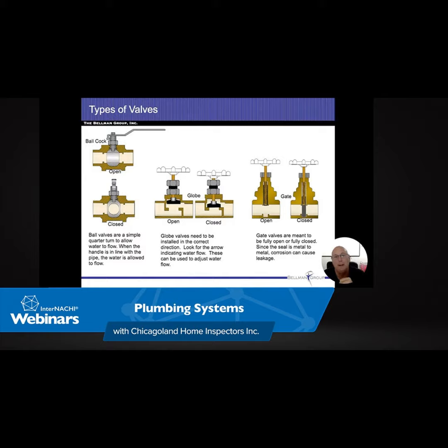But I still have the same baffles, same dip tubes, same anode rods, same pressure relief valves. Something that is different, though, is I don't have a draft hood at the top of it. With gas appliances, we're going to allow that mixture of fresh air to be taken in through a draft hood. Because oil burners are not as consistent as gas burners, they need to have something that's going to vary how much air gets mixed in there to cool the temperature off.